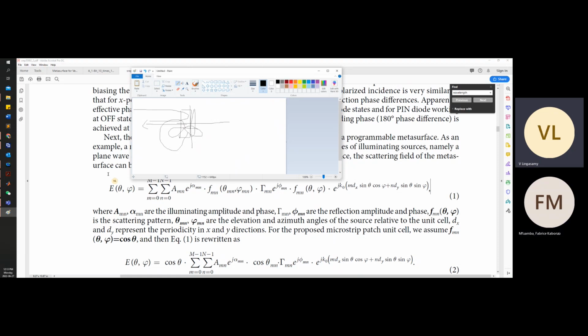Lenses, artificial lenses, all are working on a similar principle only. If you are reflecting back, then you call it a reflectarray. If you are transmitting, then you can call it a frequency selective surface, which is in the analog domain basically. In the time domain or phasor domain, you can call it a transmit array. So it all boils down to the same point, phase composition.